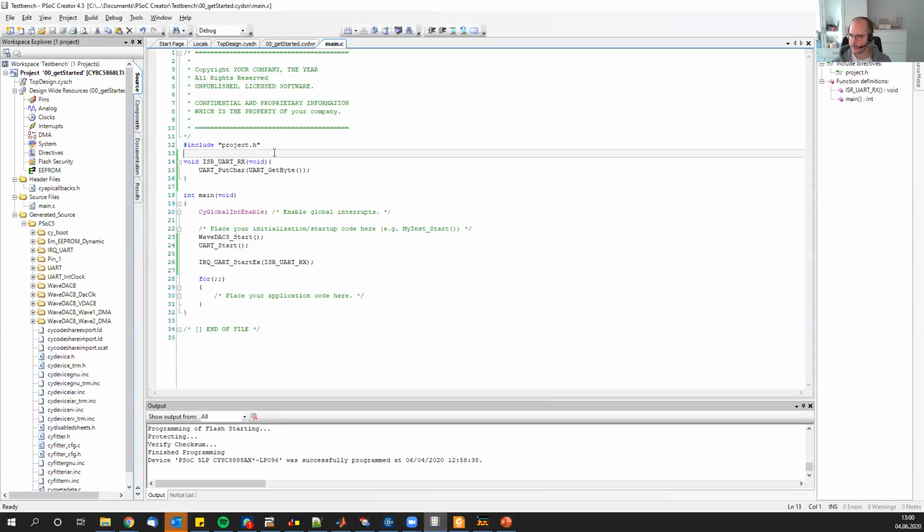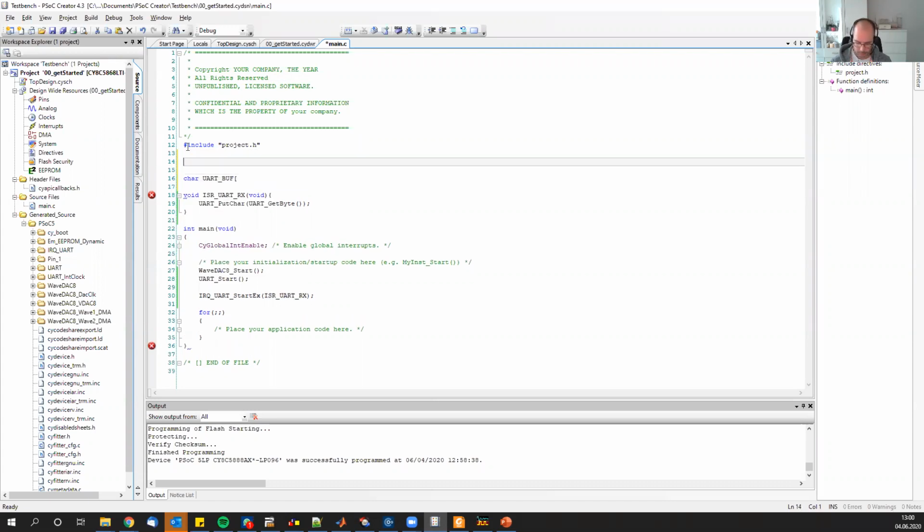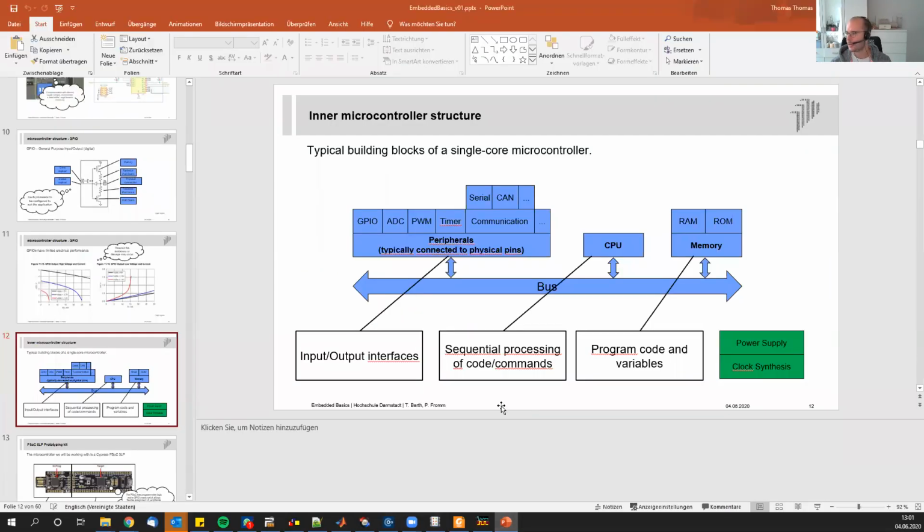I think I already did that also with you guys, that I created this buffer, and then used the ISR to write data into it, right? Yes, Professor. So in that way, actually, the storyline would be a little different. UART notifies the CPU via an interrupt that there is something available. We read the data out from the serial and put it into RAM. Yeah, good. This is one way to do it.